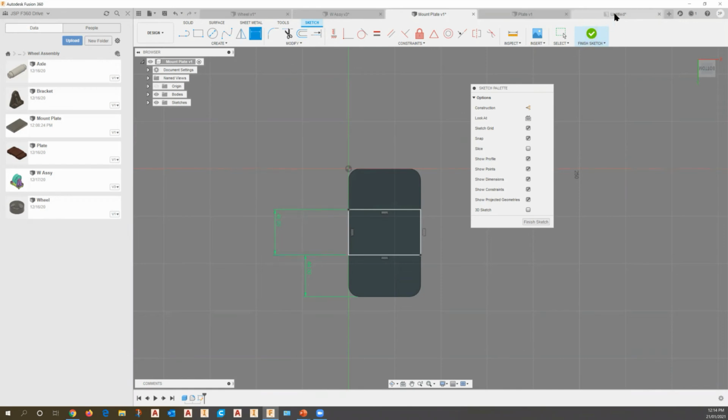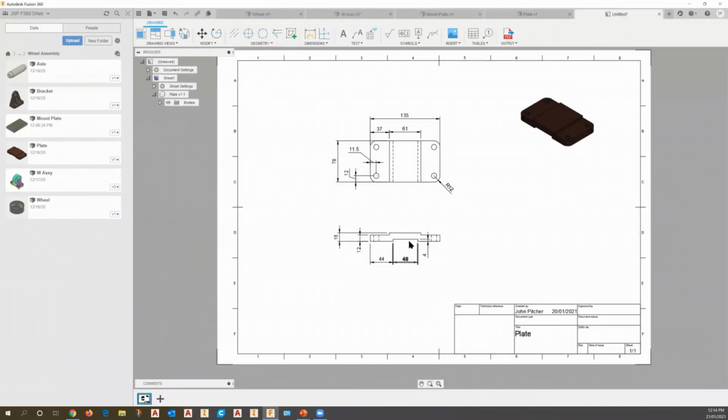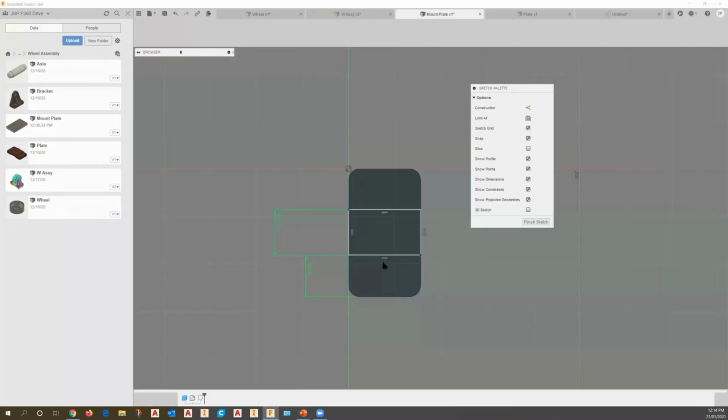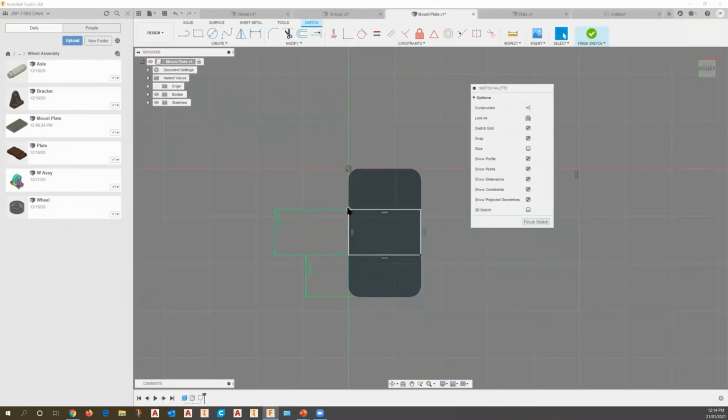All right, I'm confident that's right. So, yep, 48 wide and 44 in from the end. So basically what I've done is I've just drawn a rectangle, 44mm in and 48mm wide. It's the same width as the part, and you'll notice when I click here, it automatically snaps to the previous geometry on my part file.